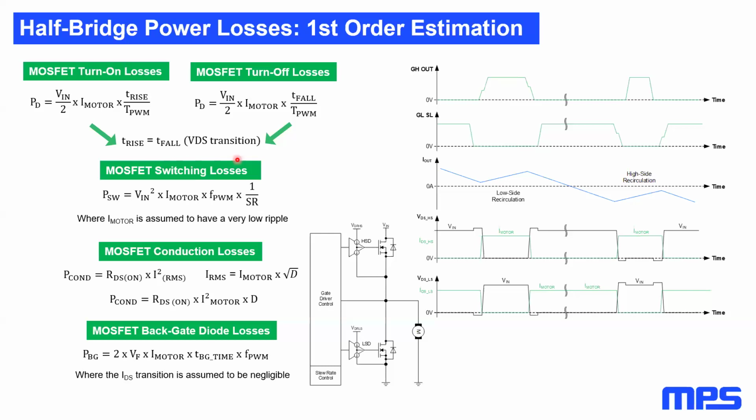If the current flows into the switching node, the process is reversed, because the body diode of the high side will be the one carrying the current during the dead times, and the high side will have this advantage of not needing to sweep its VDS too much while the current is flowing through the body diode.